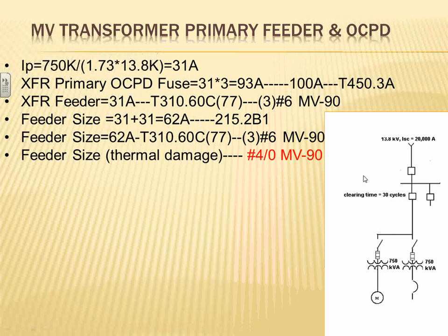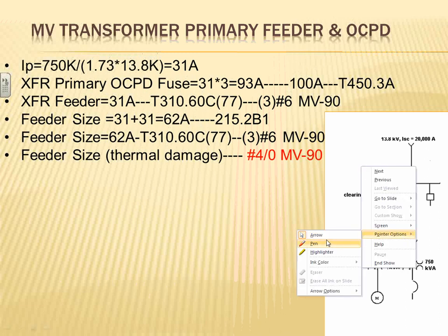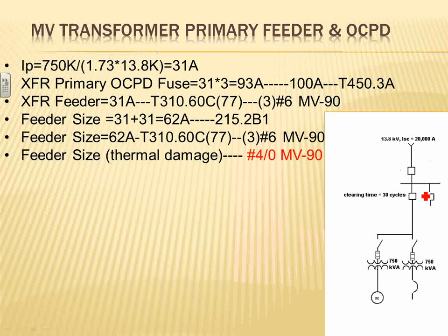So if you want to know, you have to get a little bit deeper, then you get into the setting of your overcurrent protection device. This is the worst scenario that could happen to you. Utilities use them all the time. If you have a short circuit of 20,000 amps and the voltage is 13.8, and you want to allow the short circuit to sit in your switchgear for 30 cycles. 30 cycles is half a second.